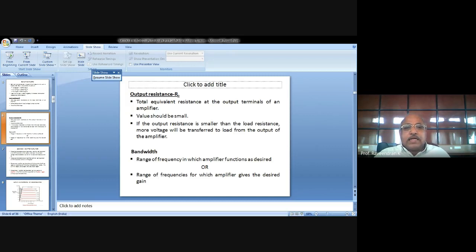So in effect what happens? IC in the circuit is almost independent of transistor parameters. The transistor parameters are VBE, beta, IB. So IC is almost independent of all these three parameters now. We have seen. So that is why this circuit with the voltage divider bias gives a very good stabilization, and good stabilization is ensured with the voltage divider bias. So that is why we prefer voltage divider bias compared to any other kind of bias used in transistor configuration.